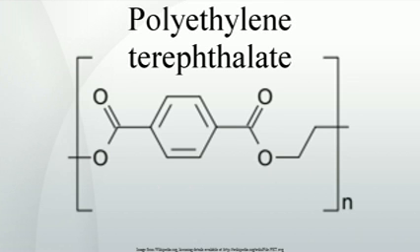PET can also be dried in compressed air resin dryers. Compressed air dryers do not reuse drying air. Dry, heated compressed air is circulated through the PET pellets as in the desiccant dryer, then released to the atmosphere.